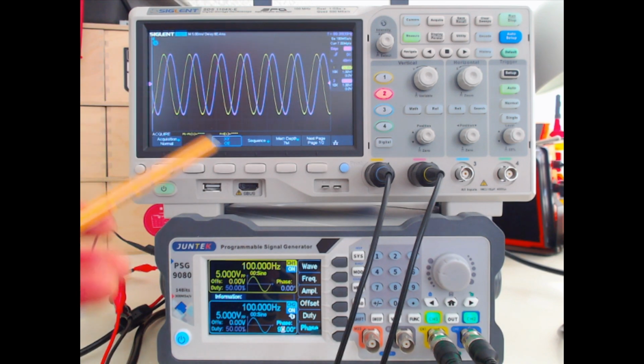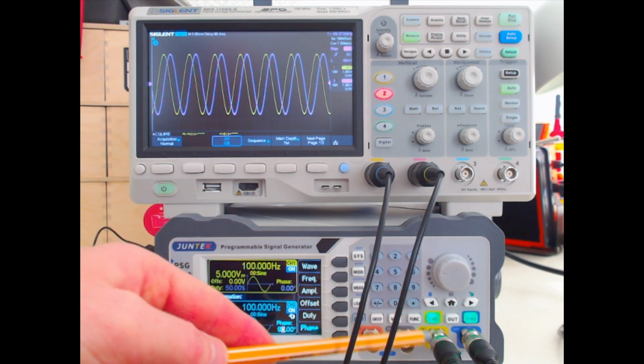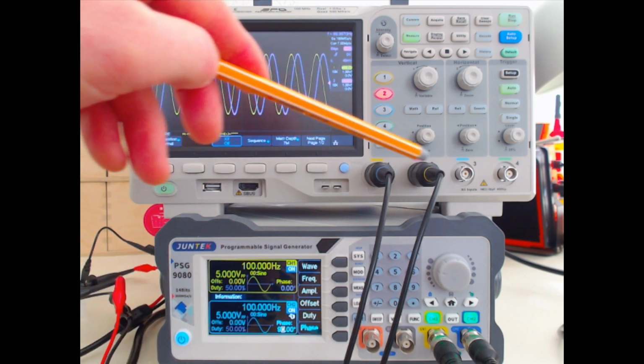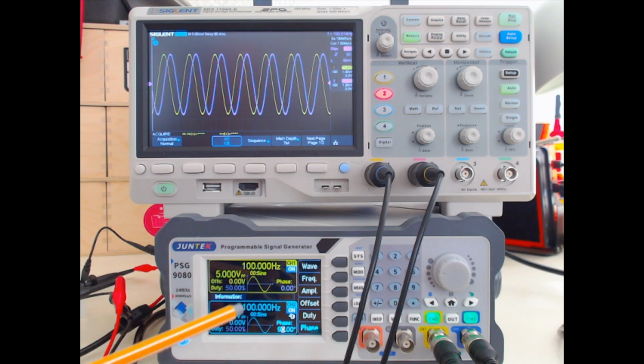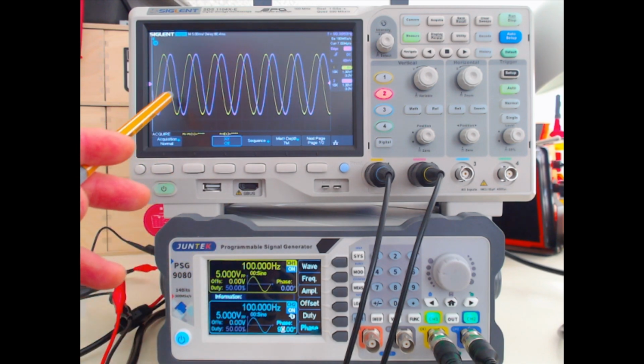What we've got here, across these 2 channels, which go into the scope's channels respectively, is 2 sine waves, both at 100 Hz. The frequency doesn't matter, only that the frequency is the same in this case. Also, you can see that these 2 waves are 90 degrees out of phase with each other. Or rather, one of these waves is a sine wave and one of them is a cosine wave.